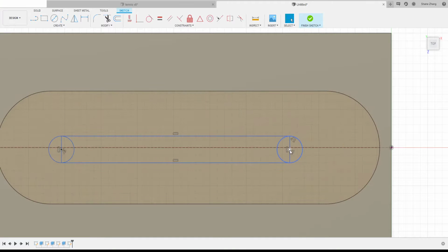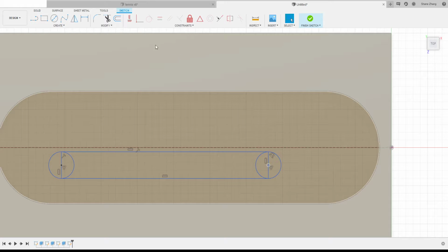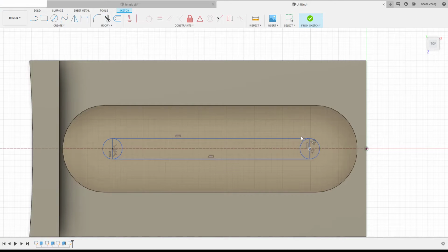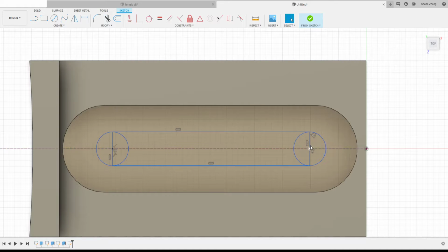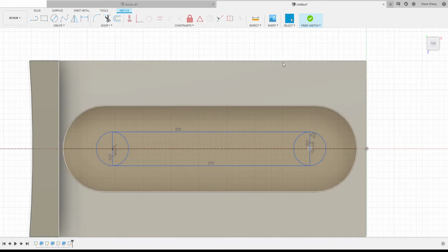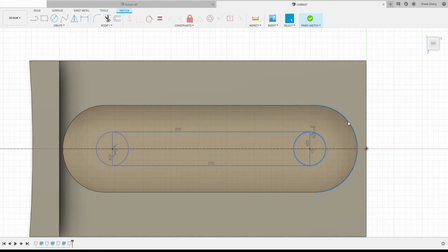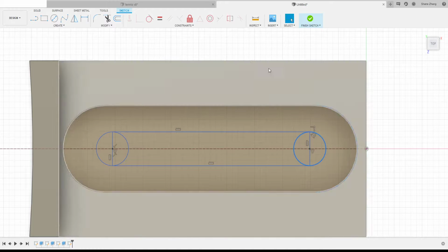Then, so you don't have to drag to put on the line, what you can do is, we have a coincident. So do a coincident constraint. I think I already have the point selected. So pick the construction line and escape. So this way it's the same as you trying to drag and make the point stay on the construction line. Alright, then we also need this center to be on this center. So you can do a couple different ways. You can use a coincident. You can pick this corner, pick this dot, and pick this dot, do a coincident. Or I can pick this circle, and I'm going to hold the control and pick this arc. So I have two circles selected. I'm going to do a concentric.